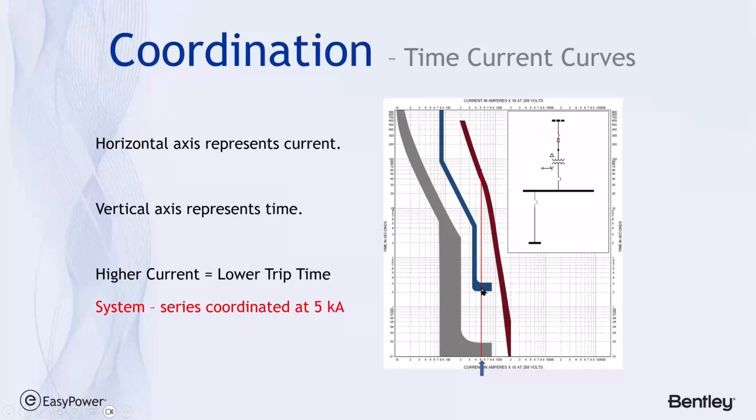But it's the same principle in that the breaker starts to sense the fault at the lower end of the plot, and the upper right hand corner edge of the plot is where the manufacturer tells us it will clear the fault. So if 5,000 amps was applied to this breaker, we see it's about 300 milliseconds response for the low voltage power circuit breaker.